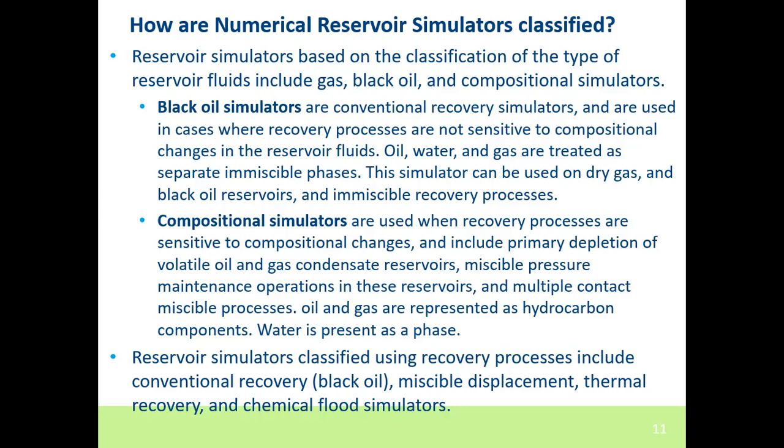For these systems, representing the reservoir fluid by just the bulk oil and gas phases will be insufficient. You need to represent the reservoir fluids in terms of hydrocarbon components, and water is treated as a phase.